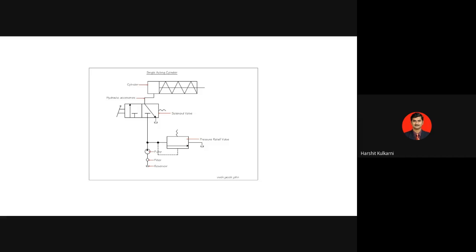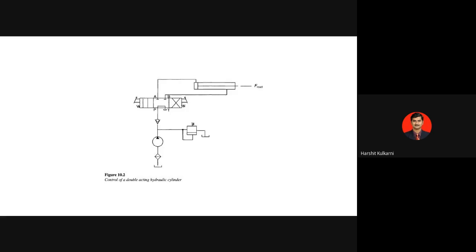Next comes how it is operated. It is lever operated. During extension this push button is there, but during retraction, what is it? It is spring return. Fine. And here it is written that it's a solenoid valve. So you name it as 3 by 2 solenoid actuated spring retracted directional control valve. Okay. Fine. So like this, let me know how you can name this.